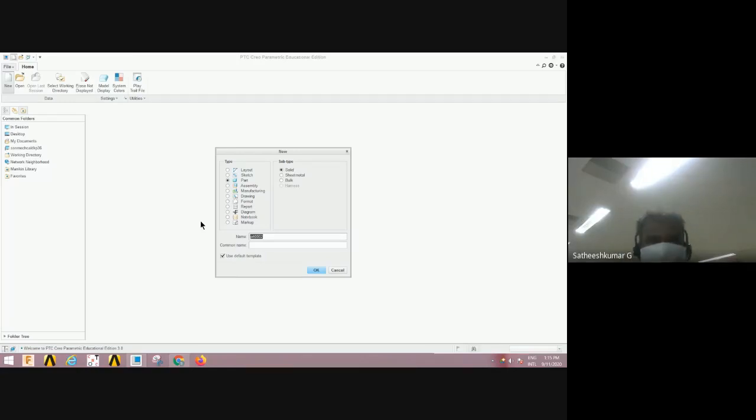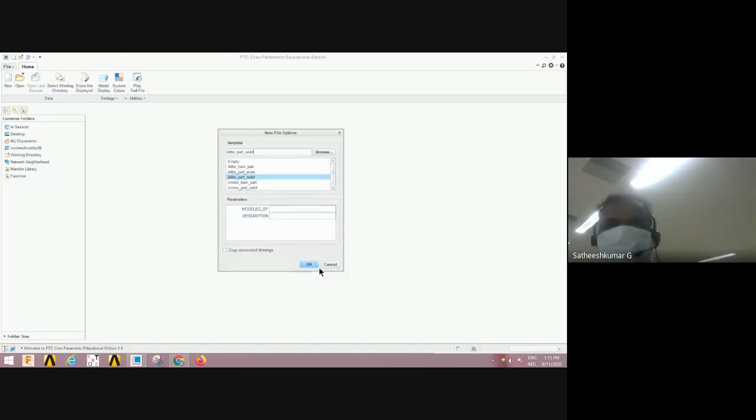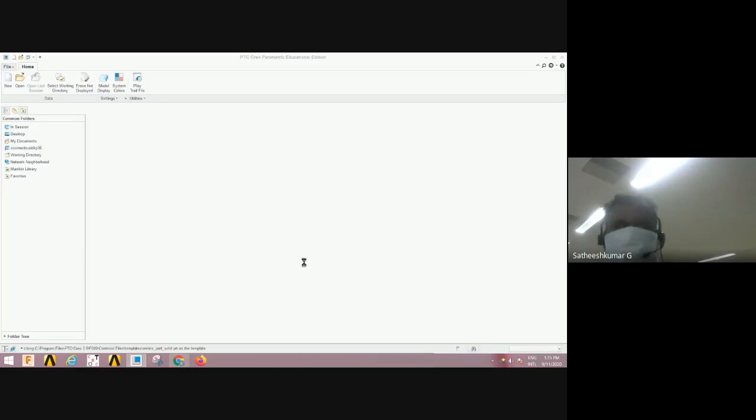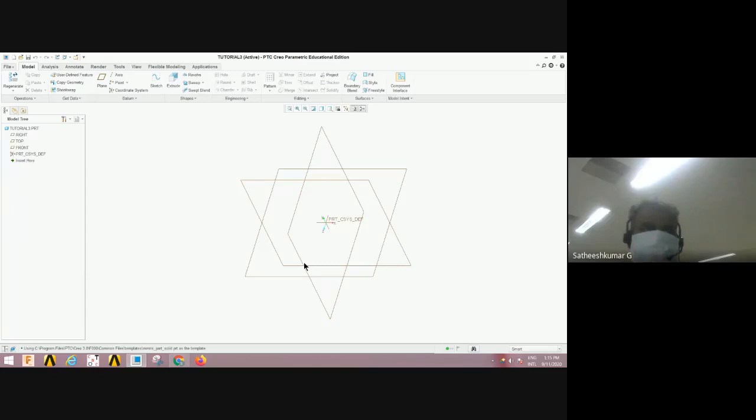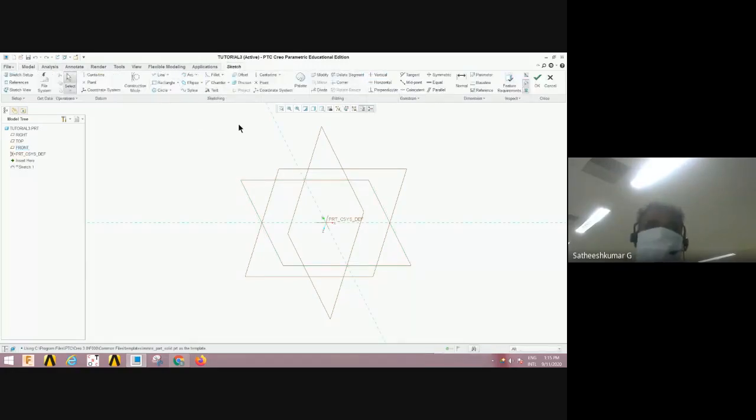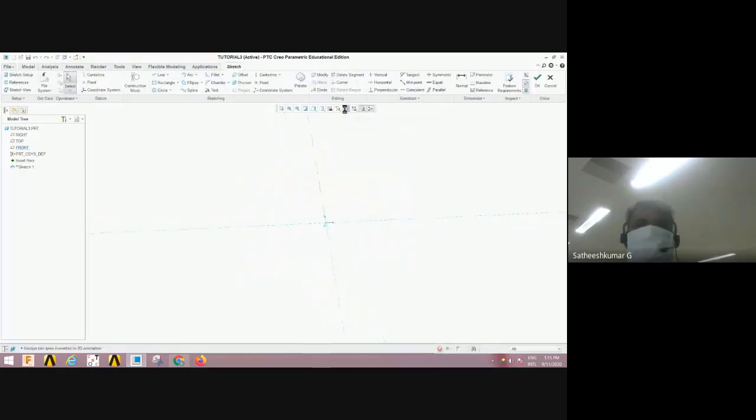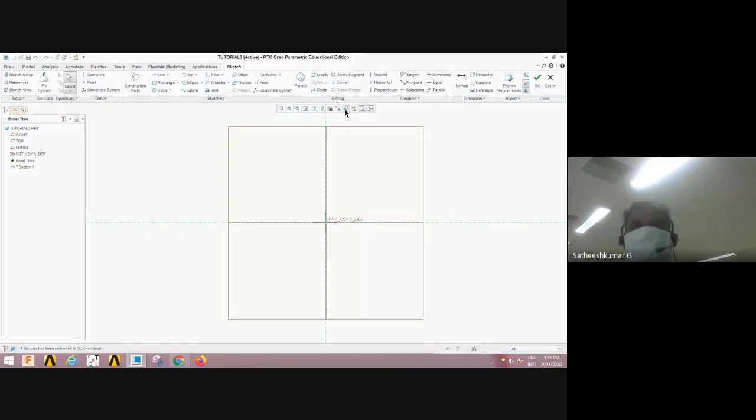So, as usual, the name, it's up to you to create your own name. So MM is what we choose. We have to choose a plane and then choose the sketch option and the sketch view for us to start the sketch.